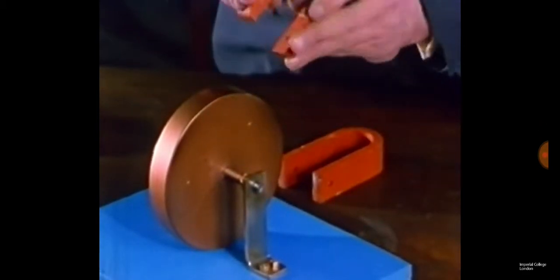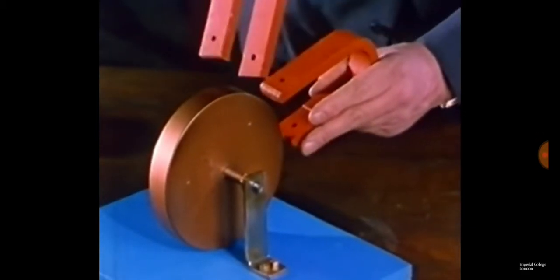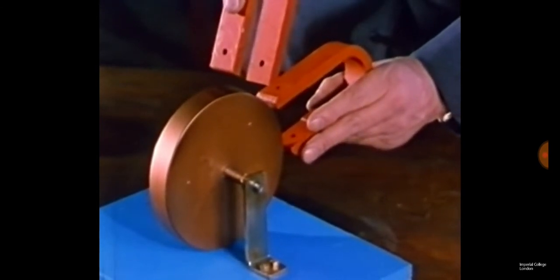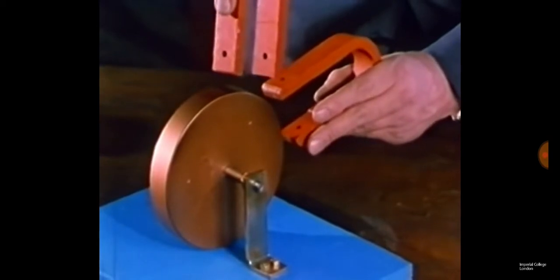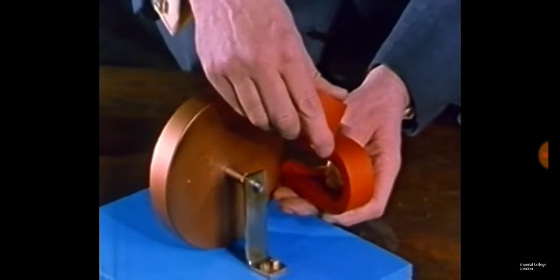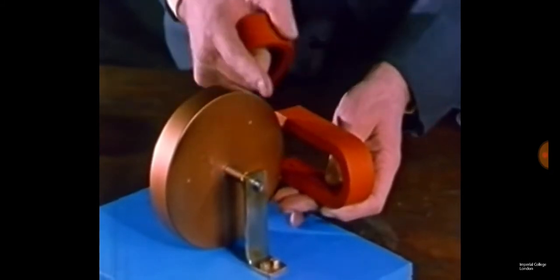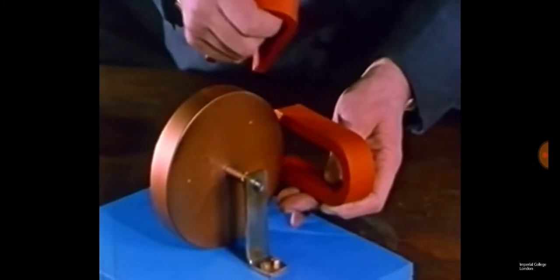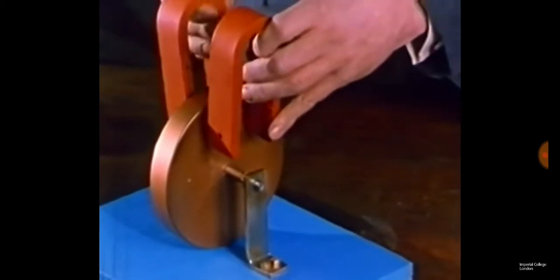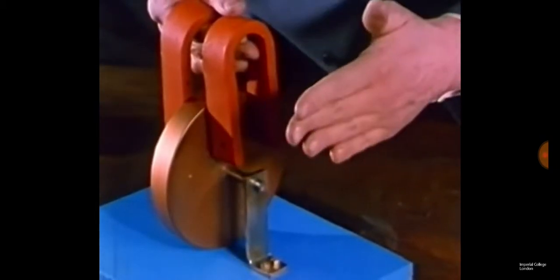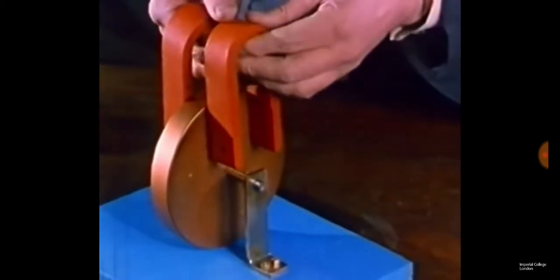Yet another man said, let's put the magnets on the edge of the disc and make the disc into a cylinder, elongating it axially. They realized that this was going to make rather a large diameter motor, and so they said, well, let's fold the magnets over like that. And now, realizing that they were using the side of the poles rather than the front, they said, well, if you can do that, then you can put the magnets like that. And in this case, you can now put another disc here and then have another set of magnets and so on and make a long machine that way.